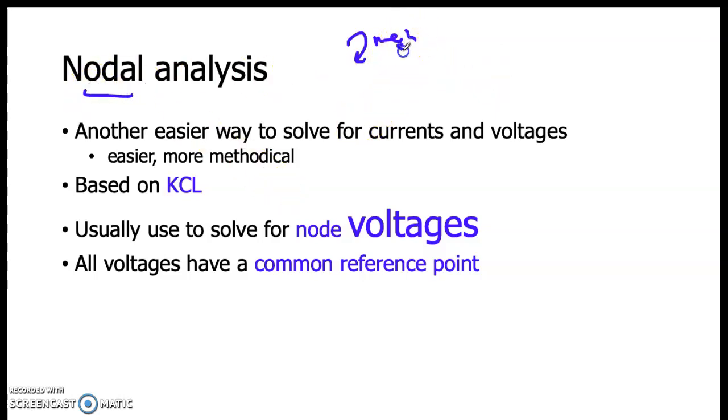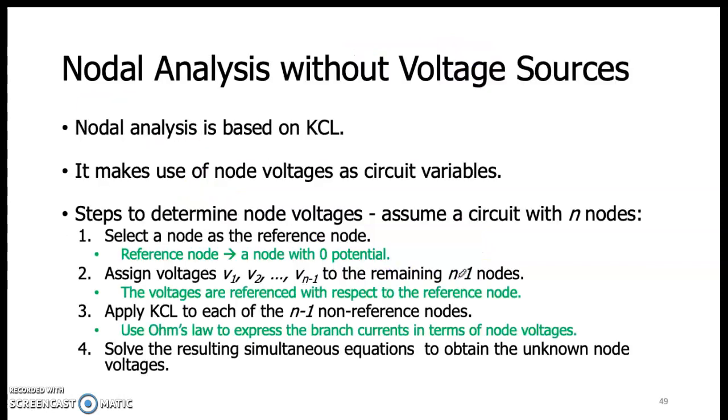So if you look at the mesh you use KVL, right? But for the nodal you use the concept of KCL. Okay, so to solve for the node voltage, any node voltage, usually the essential nodes, and all voltages have a common reference point, the one that is referred to as the ground. Because there are several steps here.